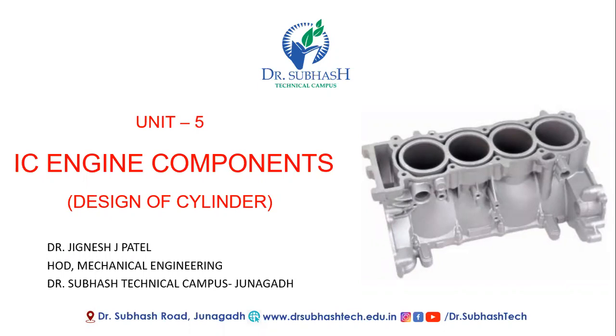Now, as you know, the principal parts of an engine are the cylinder and cylinder liners, piston, piston rings and piston pin or gudgeon pin, then connecting rod with small and big end bearings, then crank, crankshaft and crank pin, and valve gear mechanism. The design of all these components we will learn in later videos. So today let us start the design of the IC engine cylinder.